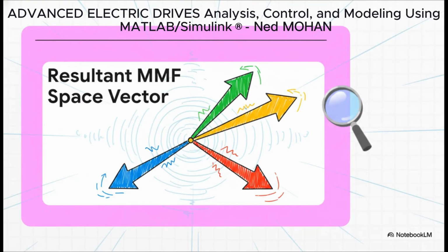And here it is, equation 2-20. This is basically the magic formula. It tells us that this resultant MMF space vector is just the vector sum of the instantaneous MMFs from phase A, phase B, and phase C. You just add them up vectorially. And just like that, poof! We've gone from three complicated interacting things down to one single elegant vector. It's really that simple.